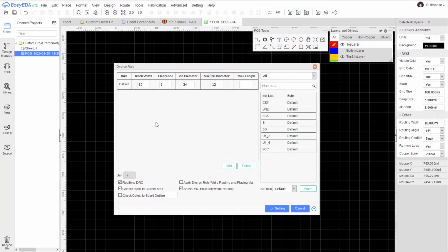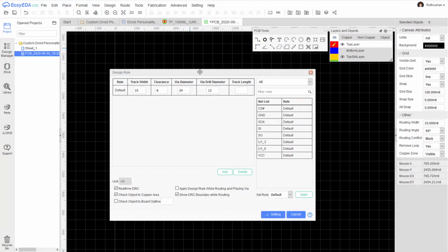This is where you specify minimum trace width, minimum silkscreen width, minimum distance between traces, minimum distance from holes to other things, minimum distances, tolerances, that sort of stuff. In EasyEDA, their defaults are going to be at or more conservative than what OshPark, for example, needs. So you could leave them as is, or you could go online and find the page on OshPark's website that talks about what their minimums are.